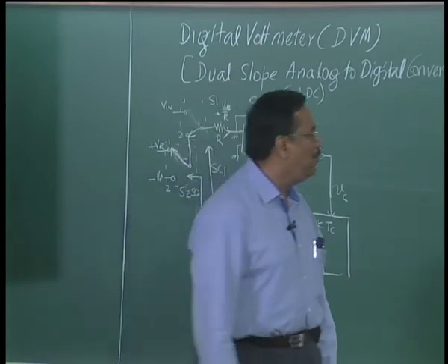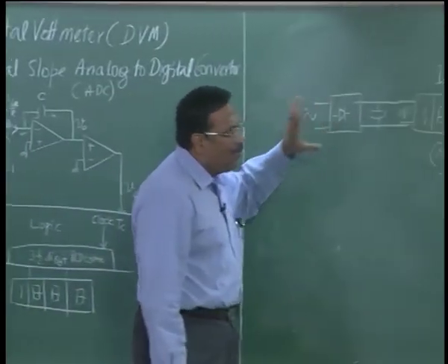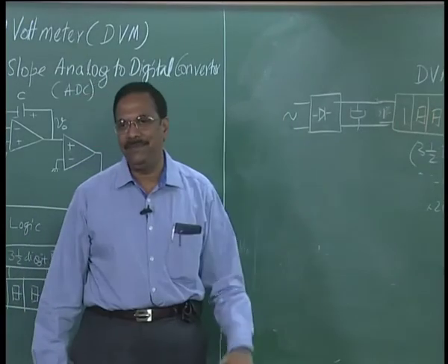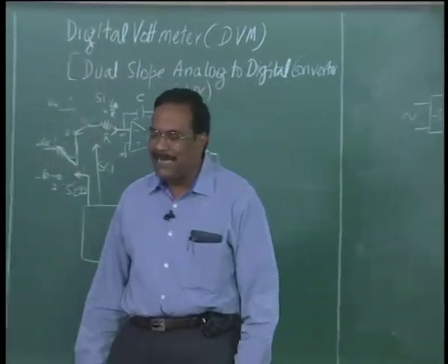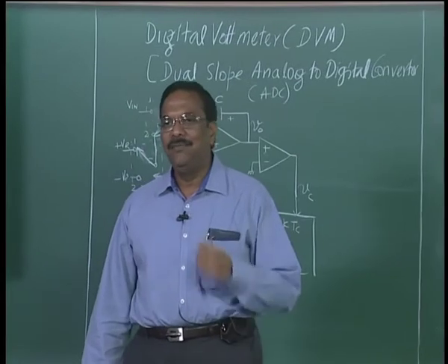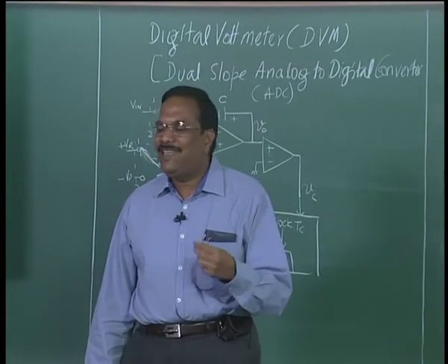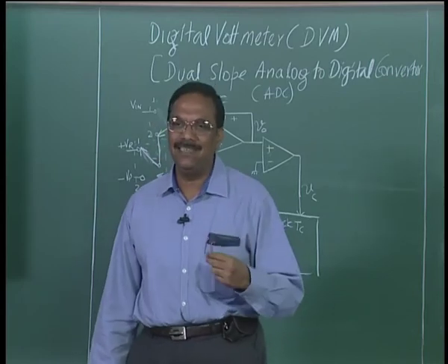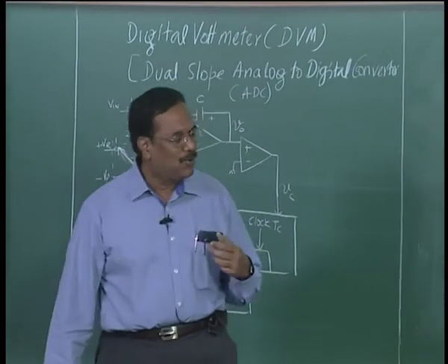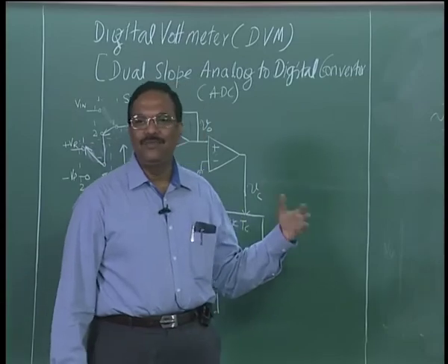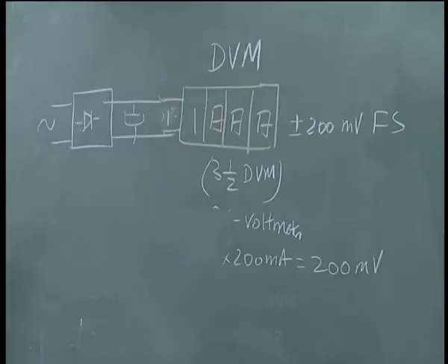So if you look at most of the low priced digital multimeters, you will see multiple ranges in DC voltage, multiple ranges in DC current, right, but you will see only 2 or 3 ranges in AC voltage, mostly 20 volts AC, 200 volts AC and 2000 volts AC, right, because below 20 volts AC the diode drop becomes such a big problem, right.